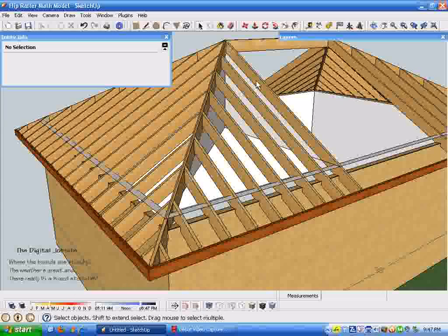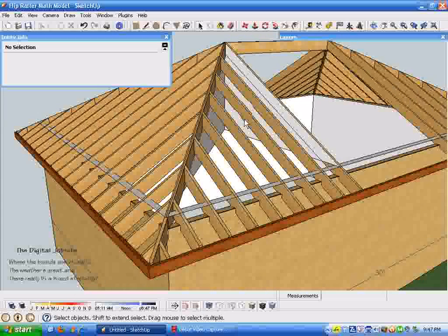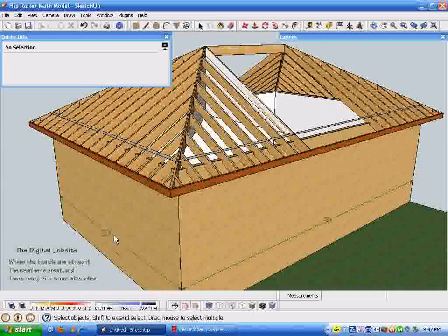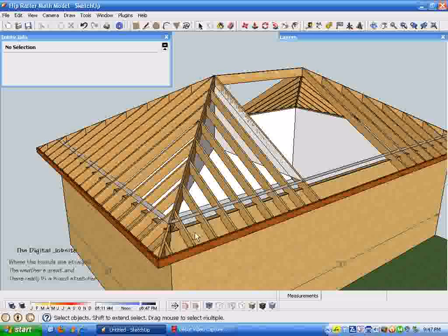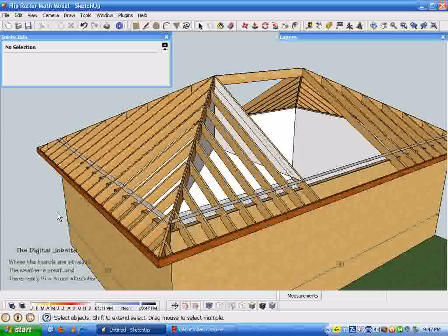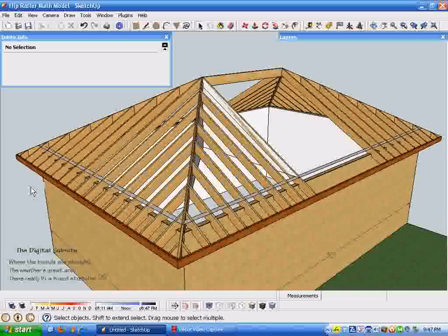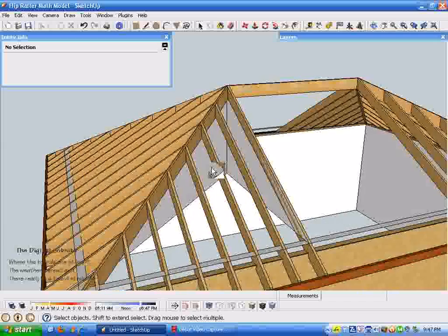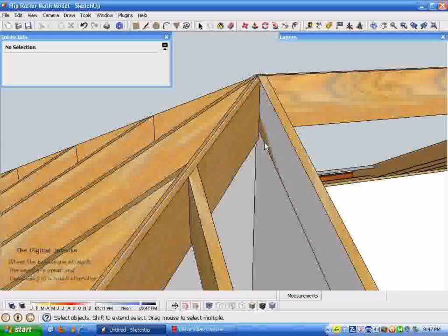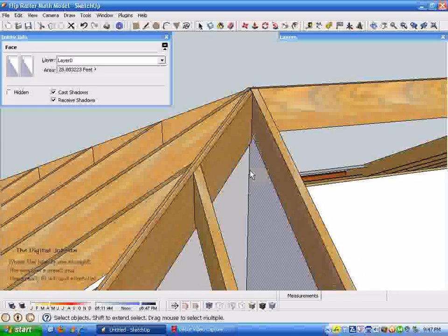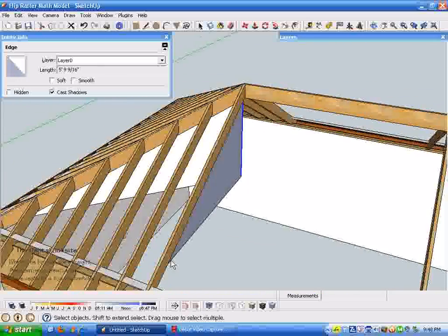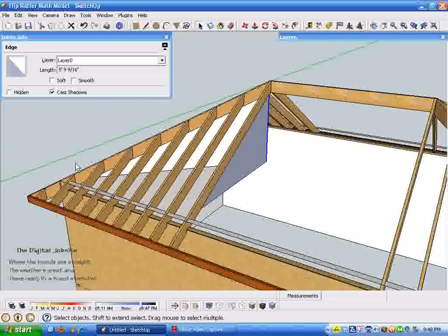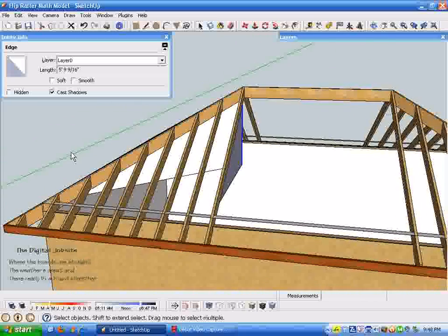But when you start changing things, if you've got a 9 1/4 12 pitch, or if you've got a 17 foot 2 1/2 inch run, any of those things, as you start to change those, it gets trickier, more complex to do these things with a rafter table or a construction calculator. And even then, you need to understand what the calculator's dimensions are giving you, what they represent on the actual rafters themselves. So I like the model and measure method,